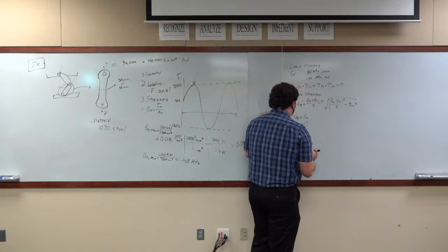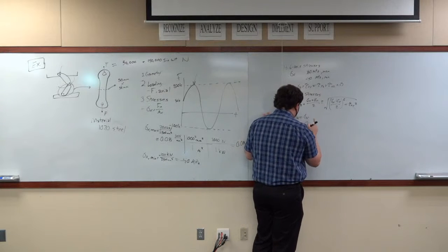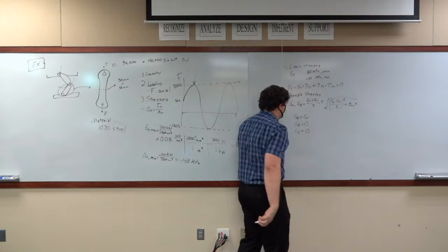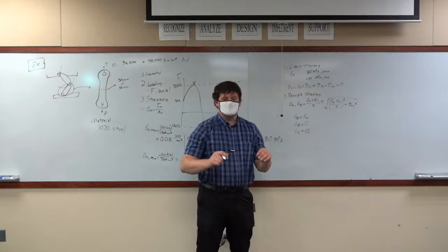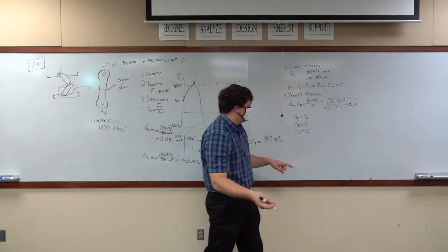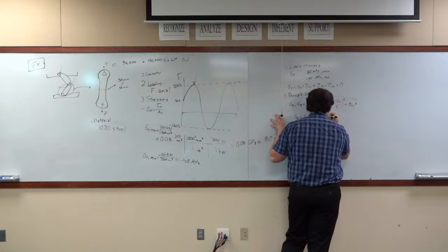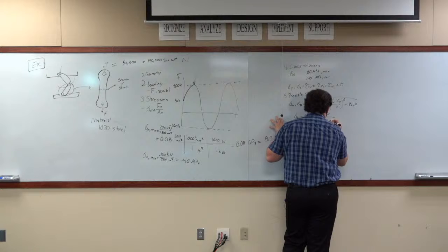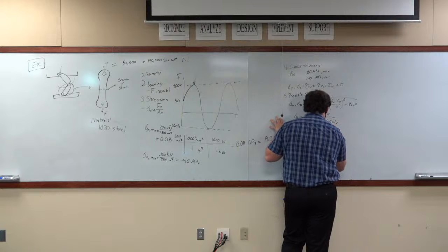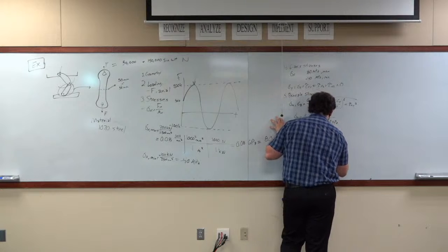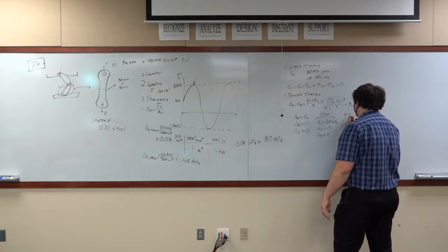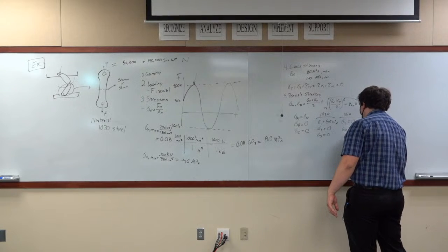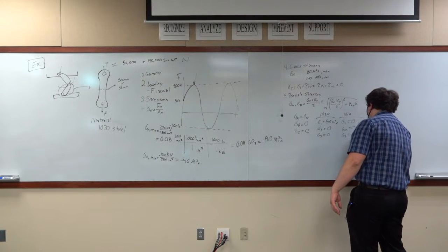So our three principal stresses are going to be sigma x, 0, and 0. Which means our two principal stress states are at max loading, sigma 1 is equal to 80 megapascals, sigma 2 is equal to 0, sigma 3 is equal to 0. At the minimum loading, sigma 1 is equal to 0, sigma 2 is equal to 0, and sigma 3 is equal to negative 40 megapascals.